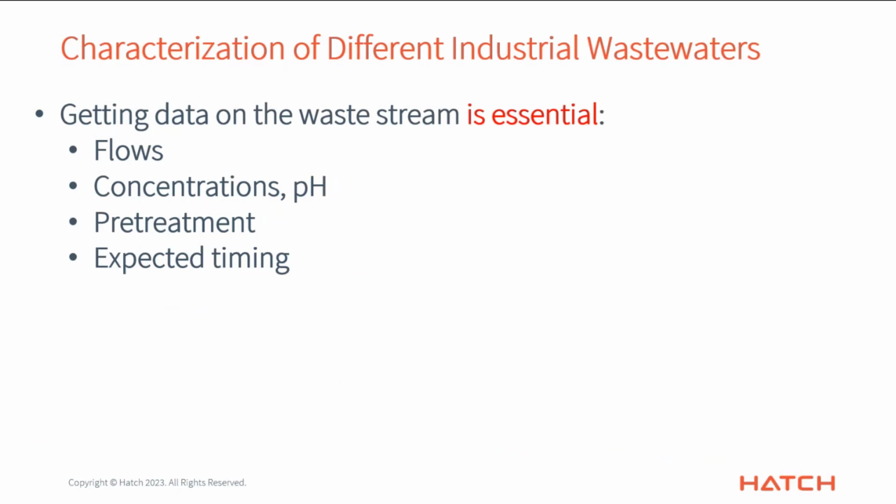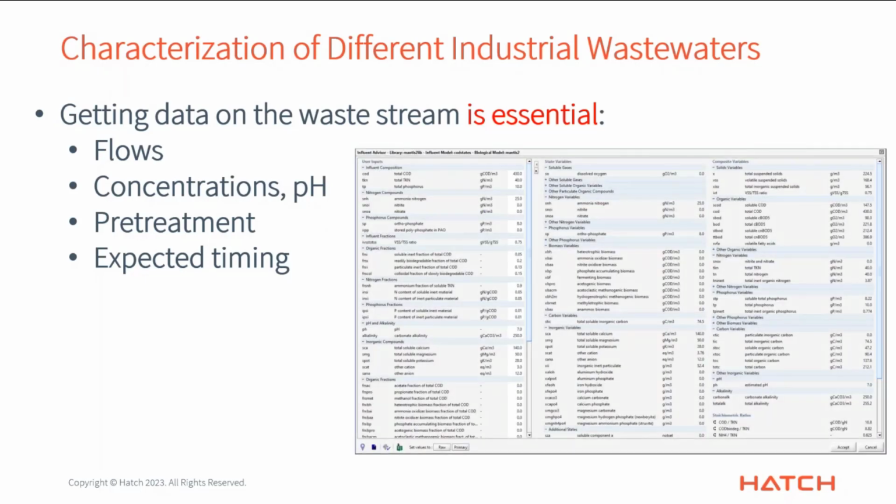So you're going to want to get, for sure, at least the flows as you best understand them, the concentrations of those things that we discussed earlier, the pH, an understanding of what the pre-treatment is doing and what it's supposed to be there for, and the expected timing. And again, nobody knows. Sometimes it just happens, but nonetheless, an understanding of what to expect would be helpful.